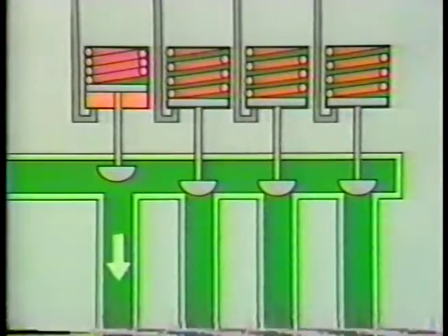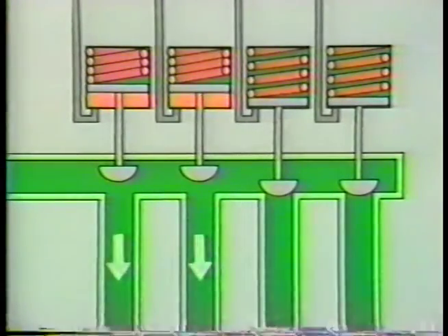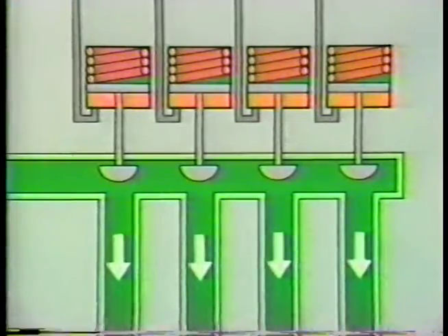The control valves are operated by hydraulic actuators. These valves regulate steam flow to the turbine by opening and closing in sequence. As each valve opens, more steam is admitted to the turbine. At normal turbine operation, the control valves are positioned as necessary to compensate for changes in load. At full load, all the control valves are almost completely open, allowing a full flow of steam to the HP turbine.